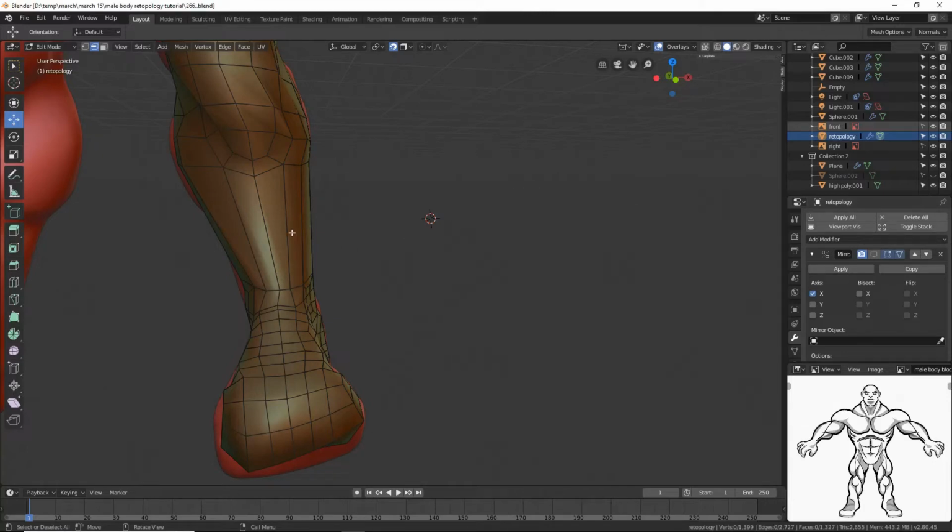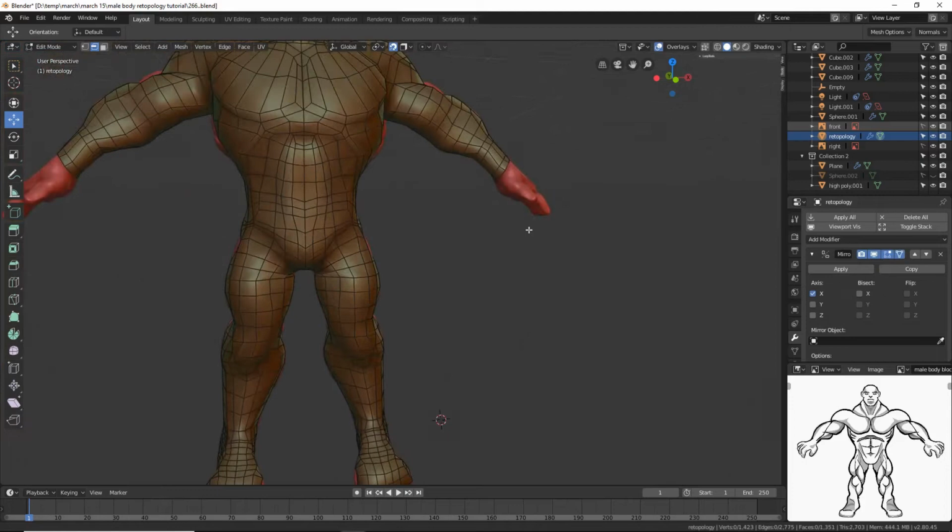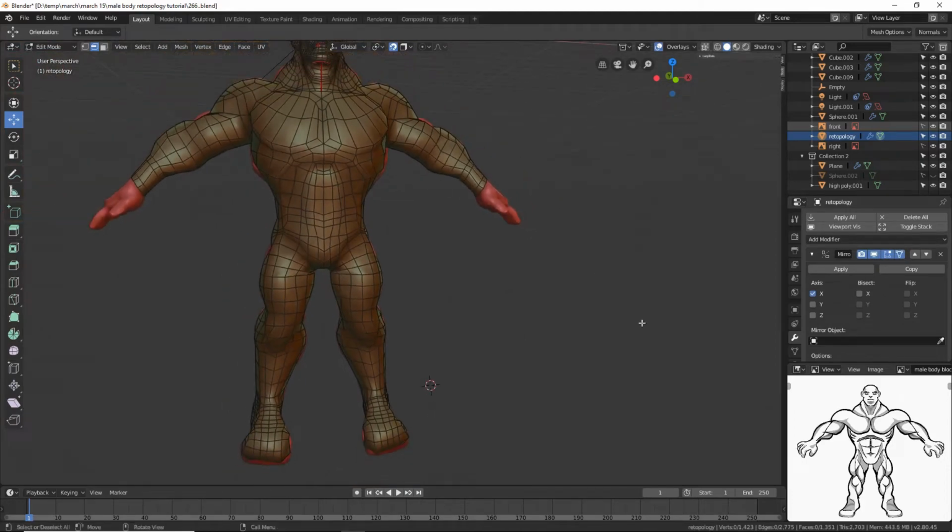Okay, I'm going to hover here, hold Control, press R, roll the mouse wheel once, left click a second time to lock in. Then left click on nothingness to deselect. I'm then going to click on this monitor so we can have our mirror modifier back on. I'm holding Control as well as the middle mouse button to zoom back.